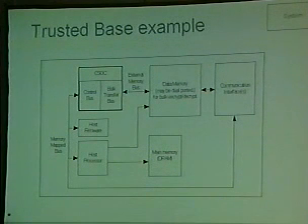It also shows, by that memory mapped bus, it'll control the communications interface. There'll be 2 buffers, an encrypt and decrypt buffer, and the CSOC will be told to do an operation on one buffer and then tell the NIC interface to pull it out of the other buffer, but I can go into that in greater detail in the other room.